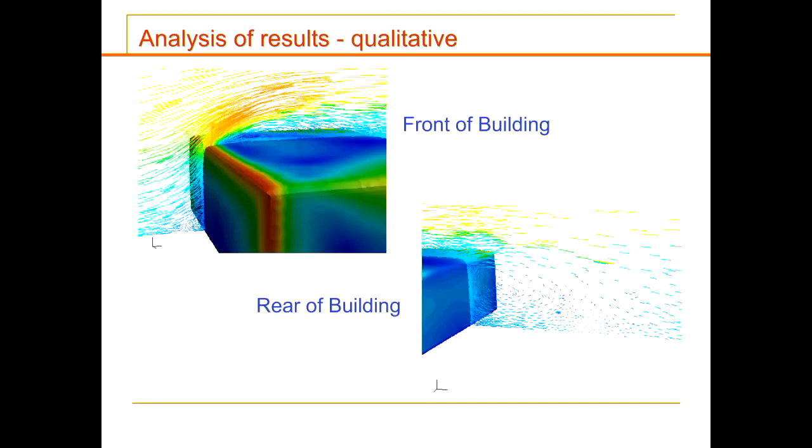So you can see that with one picture, I can tell you a lot of things. It shows the flow. The colors indicate perhaps the highest and lowest velocity. The contours on the obstacle itself show you the pressure. At the rear of the building, as expected, like a backward-facing step, you have the flow going past and a recirculation region beside it.